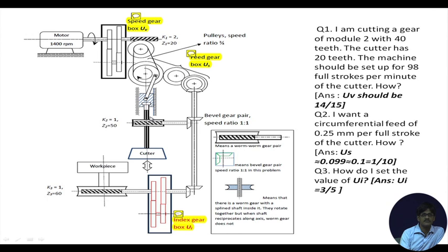In its cross section you will find, just like gears, some teeth. What is the purpose? The purpose of the spline shaft is that while it is moving up and down, it can also be rotated by a member connected with it, teeth on teeth. We will see an example both as a drawing and also as a working member in a video recording of the process.